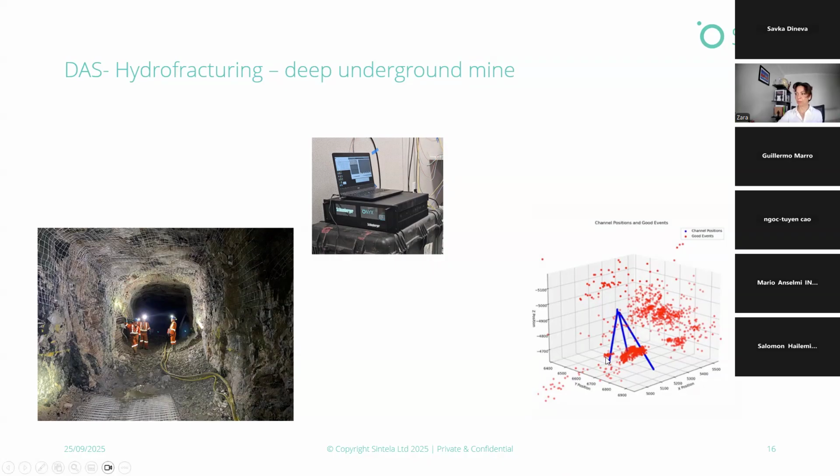So in this example, again, there were 3 short boreholes daisy chained together. These were deep boreholes, a couple of 100 meters each. With just that, for a couple of weeks of monitoring, we could see not only the seismic response related to hydrofracking, but also the seismicity within the mine, both development, blast, and seismic activity.